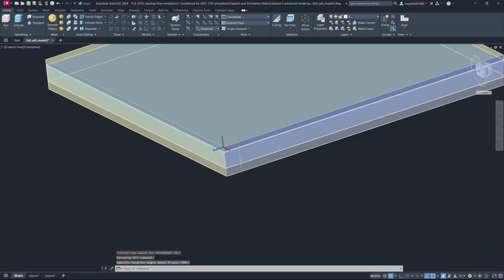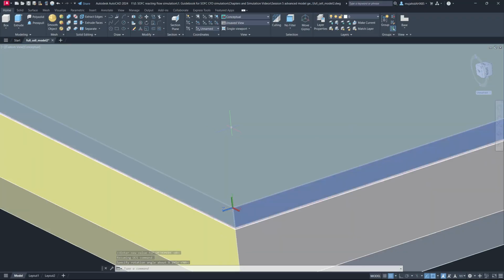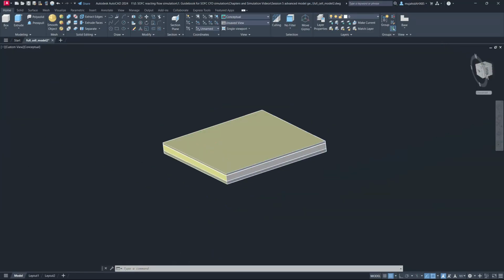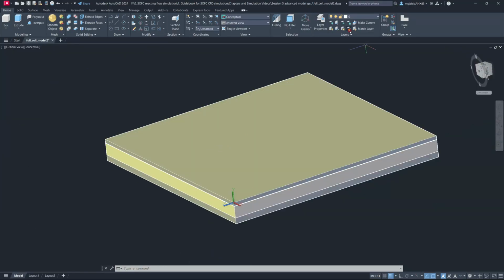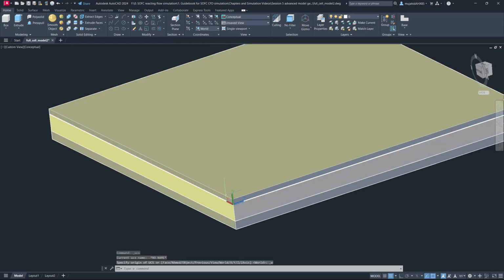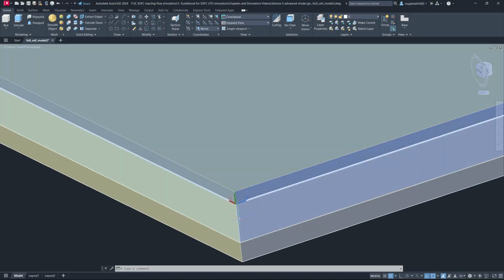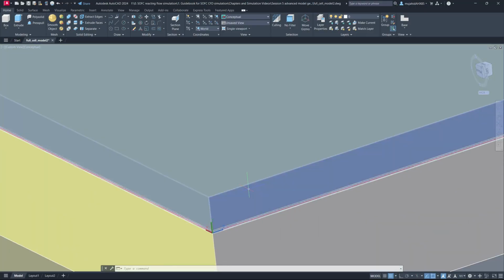So now we have the XY coordinate system. Sorry, we should go back to the global. So we need to draw the rectangles in the positive Z direction, so it is already in XY plane, so we just need to shift it. We'll just shift it into this direction.